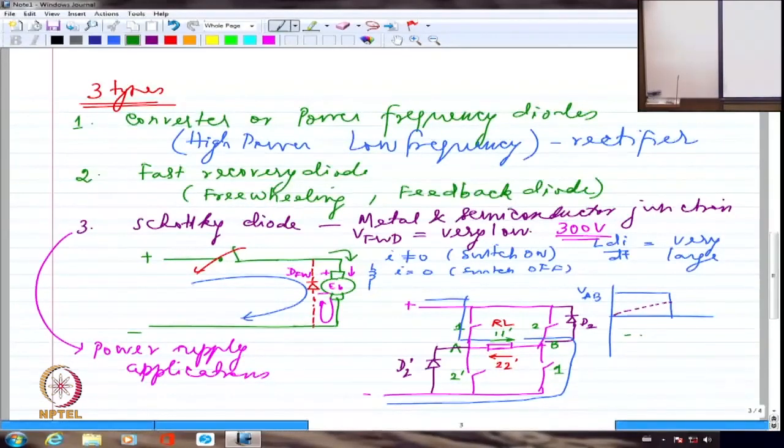So the semiconductor material can break down. So if I put a small inductance here in series with the diode, very small inductance. Very often what happens is, if I have a thick conductor connecting the diode to the DC motor drive, that itself will have an inherent inductance which is good enough most of the times.